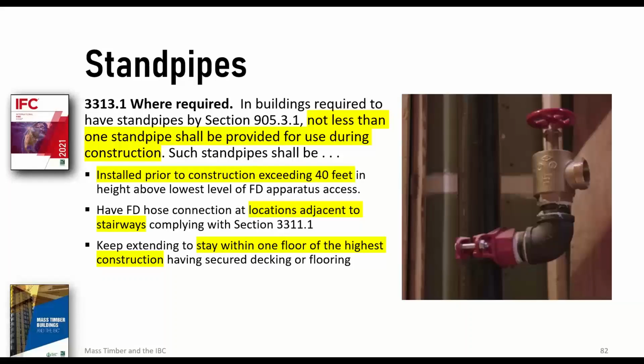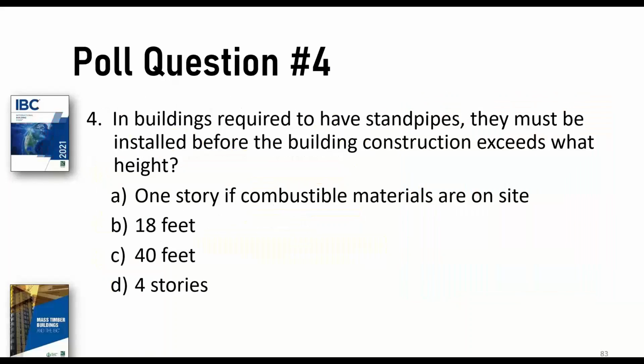The standpipe is the quickest, most efficient method to convey water to the upper floors of the structure. And minutes count when it comes to construction fires because they are so exposed. For fire departments to have to drag hose lines all the way up, or throw ladders and drag hose lines, really takes a lot of time. And it's time that the fire service really doesn't have on construction site fires. So right out of the gate that leads us to our fourth and final poll question.